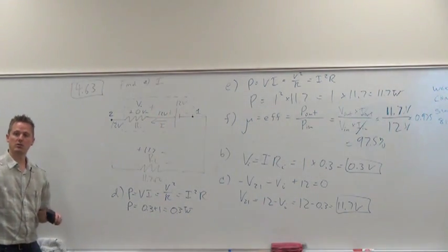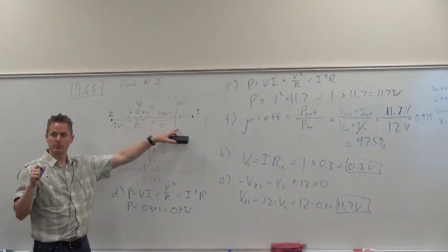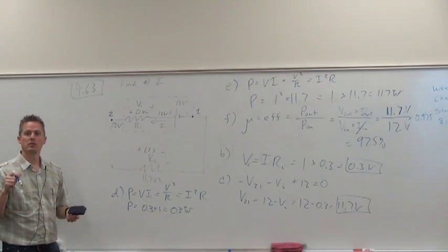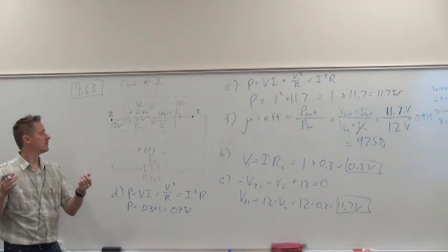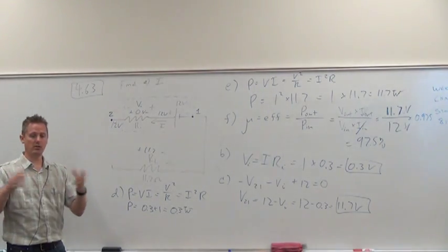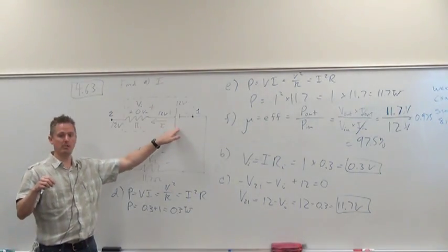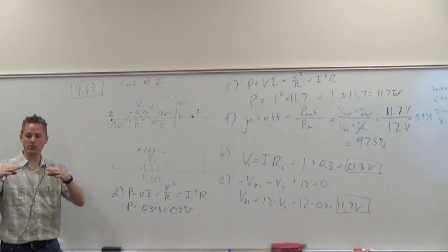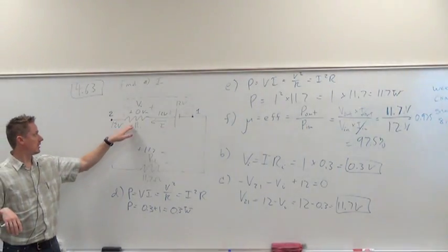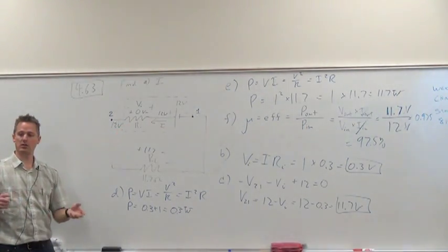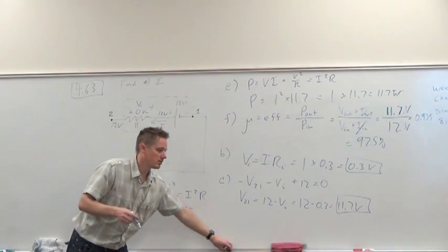So the no load voltage on a battery is the internal battery voltage. Would you be able to measure that with a meter at 12 volts? Yeah. As soon as you disconnect it from the circuit. Let's say you take a car battery and nothing's on, you measure that battery voltage. That's the internal voltage in the battery. As soon as you start to load it, the voltage is going to start to drop. And the internal resistance of that battery is actually the electrolyte, what do you call it? Sulfuric acid, mostly.